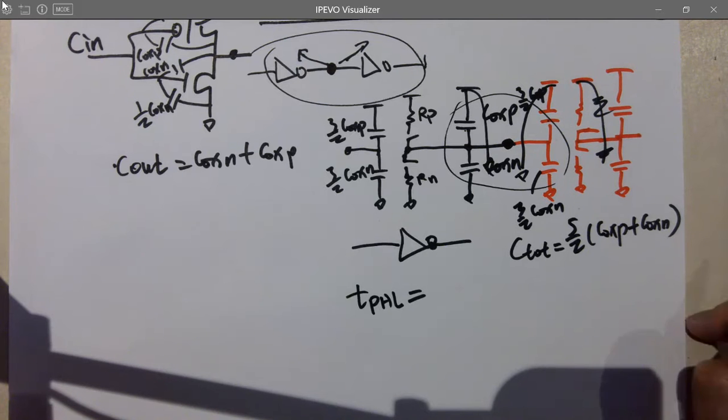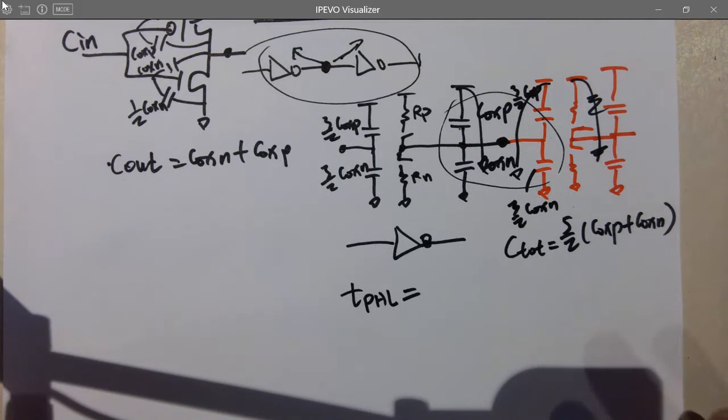Since in microelectronics too, if you go to graduate school, there will be another electronic class with a lot of AC analysis for transistors and amplifiers. Whenever you are looking at the AC signal only, you short all the DC signals to the ground, because you consider them just DC offsets. And why can you do that? What's the theory behind it?